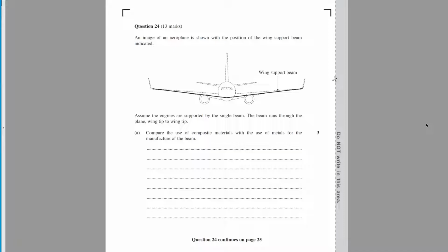Okay, so we can say that although early aircraft were typically made out of aluminium as it became more readily available, these days modern commercial aircraft are much more likely to be made of CFRP, so carbon fiber reinforced polymers. You're allowed to write the abbreviation, or composite materials. Composite materials such as CFRP or FMLs, which is fiber metal laminates such as Glare.